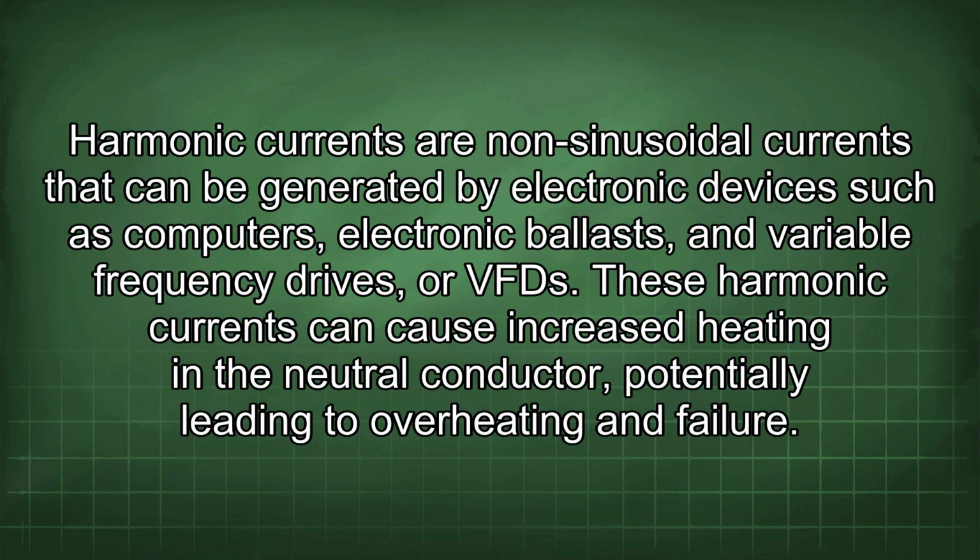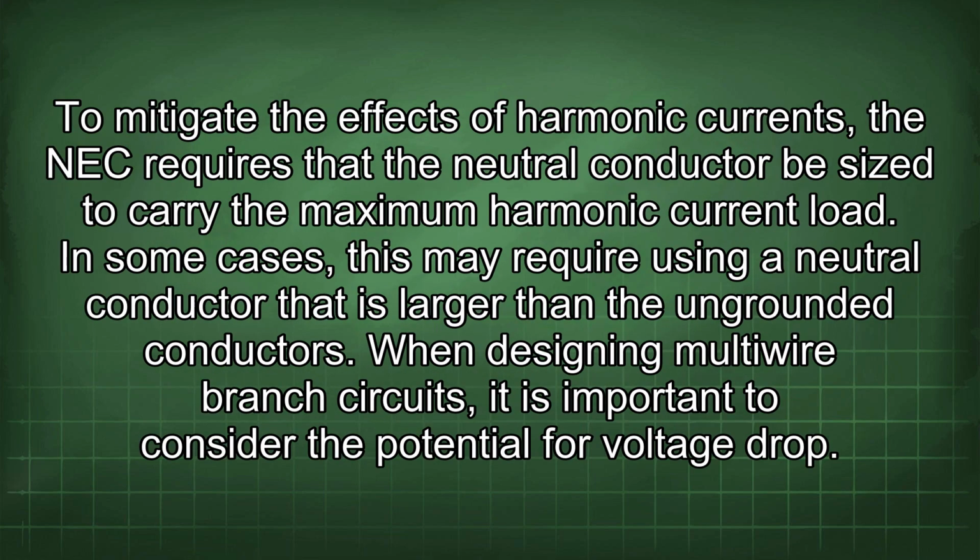Harmonic currents are non-sinusoidal currents that can be generated by electronic devices such as computers, electronic ballasts, and variable frequency drives, or VFDs. These harmonic currents can cause increased heating in the neutral conductor, potentially leading to overheating and failure. To mitigate the effects of harmonic currents, the NEC requires that the neutral conductor be sized to carry the maximum harmonic current load. In some cases, this may require using a neutral conductor that is larger than the ungrounded conductors.